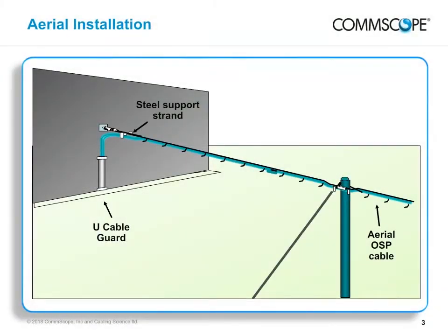Aerial installations offer several advantages, not the least of which is having a lower cost than direct burial. In addition, they can usually take a direct route between buildings since they easily cross obstructions such as roads, drains, power cables, gas pipes, and the like. Their chief disadvantage is that they tend to be more environmentally exposed, especially to wind, ice, and falling tree limbs. However, a properly installed aerial cable should be able to withstand severe weather without problem.